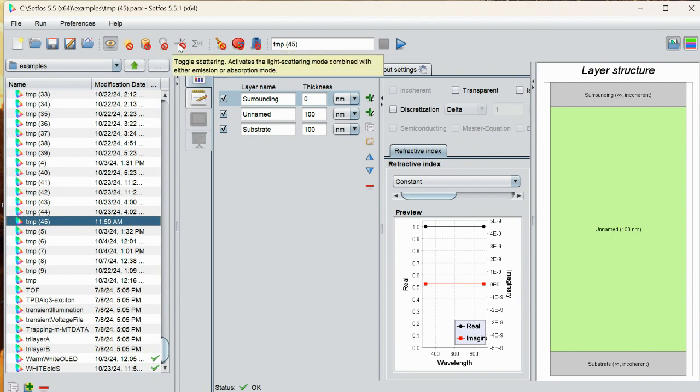All the emission characteristics we can calculate here. This is the advanced optics module, also known as the light scattering module. This is the master equations module, used to define material-specific excitation parameters. These are task mode buttons: shift mode to enable multivariable shifts, optimization mode for optimization analysis for the best results, and fit emission zone, which we can use for the emissive calculation.